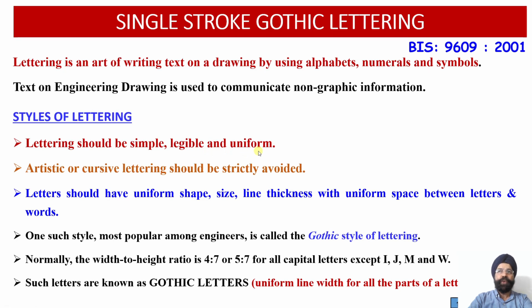We should have uniform letters. All letters should have uniform spacing, and all the words, once again, should be uniformly spaced. So there should not be anything like artistic or cursive lettering on the engineering drawing, because cursive lettering, even though it may appear very beautiful, is very hard to read. So we cannot afford any miscommunication on our engineering drawing.